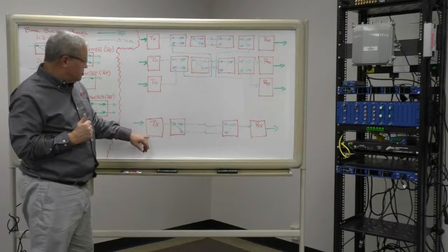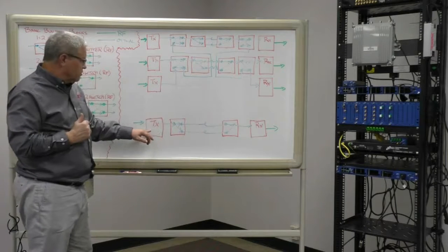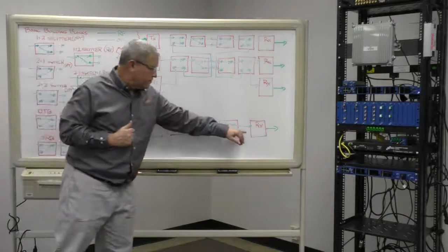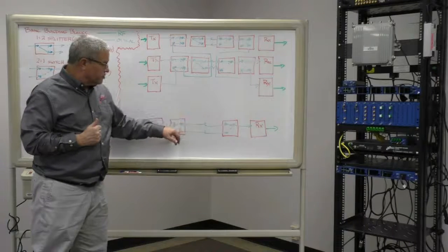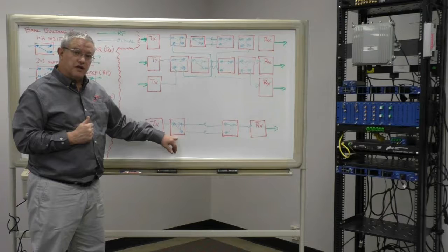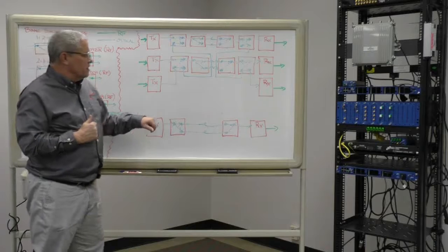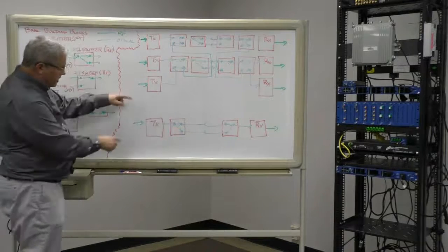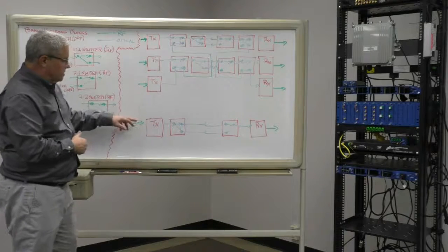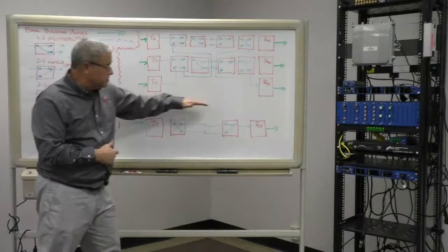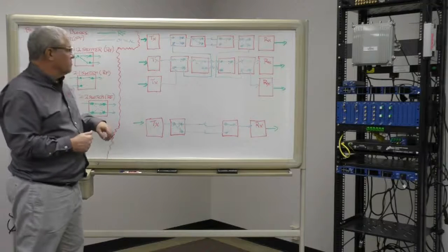In the simplest example, we're simply doing redundant fiber. So neither the transmitter nor the fiber optic receiver are protected in this case. We're just offering a diversity of paths and essentially just using a couple of basic optical switches. So this is 1x1 redundancy in the fiber. We could also, although it's not shown on this diagram, have an additional transmitter to receiver link, and switch between those and do our diversity in the RF domain essentially.